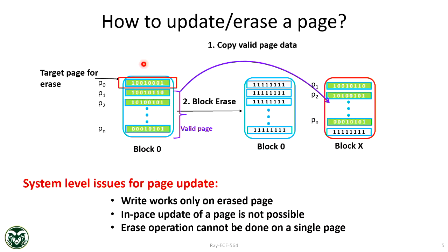So that looks like a simple problem, right? Granularity mismatch, but it causes a lot of system pain, I would say. And that's why NAND controller design is so sophisticated. You have to manage all those granularity mismatches. You also have to manage the errors in the memory bits. You also have to manage the finite endurance. If you keep using one block again and again, that block will die. So you have to make sure all the blocks are aging at the same rate, so that as a user you don't see the failure. Those are system functions, so the NAND controller actually is very, very sophisticated.